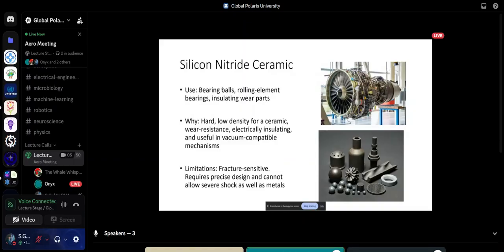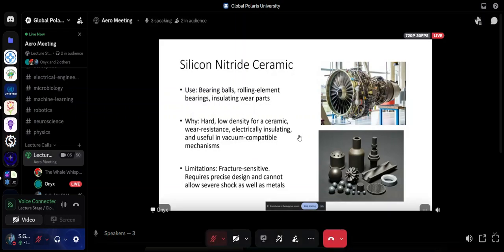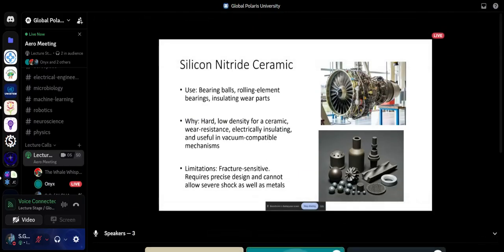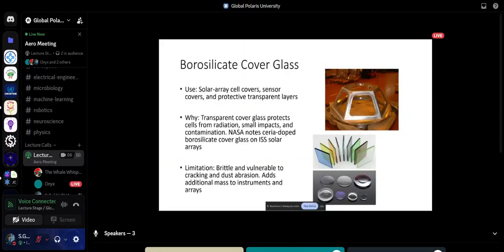Typically, I imagine for this material we're looking at, it would be homogeneous, so the entire material. Right. But there are some applications that could be used as a level of coating. A big consideration when it comes to coating is, of course, wear over time. Slowly but surely, coatings can char, coatings can melt, coatings can suffer a large amount of abrasion. So a lot of considerations like that have to be considered.